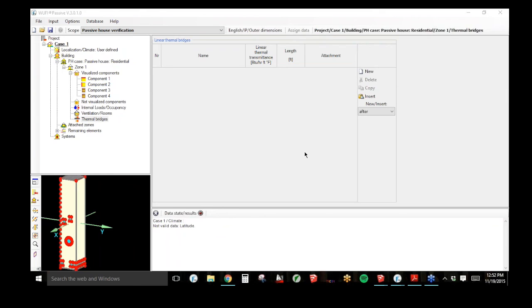Okay, could you go over drawing the window dimensions in SketchUp again? Do you draw to the exterior dimensions of the window or the rough opening, or do you draw just the glass area? Really, it's preferred, I think, to just draw the exterior dimensions of the window. If you draw the rough opening, depending on how large that is, typically that can't be that big, especially for these buildings that were very airtight. So you're trying to get that rough opening as close to the actual window size as possible, and then just sealing in between that. But if you add a half inch on each side of the window for a rough opening, that can start to overestimate solar gains because the glazing area gets bigger as you add dimension to that window. So try to just draw the exterior dimensions of the window. And then the rough opening, I guess, gets drawn into the model when you input the installation thermal bridge around the window. So it covers it there.